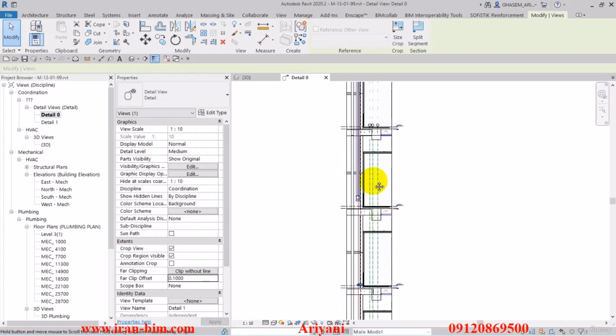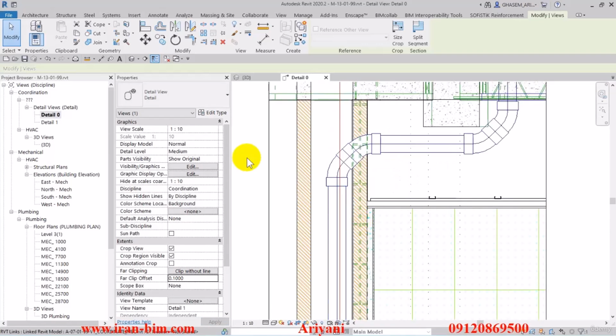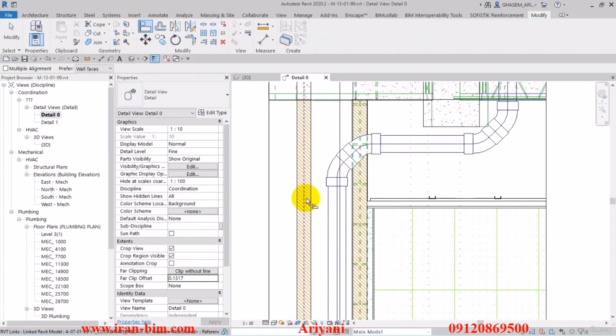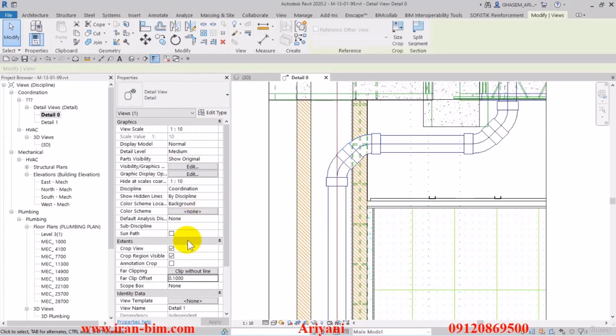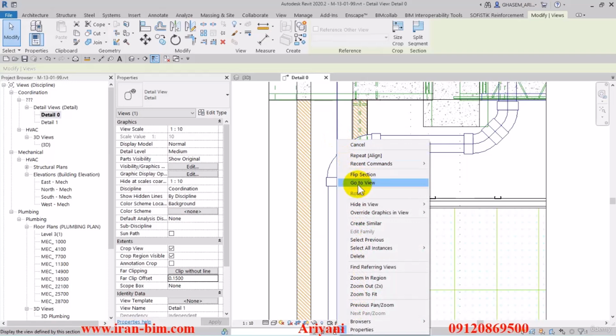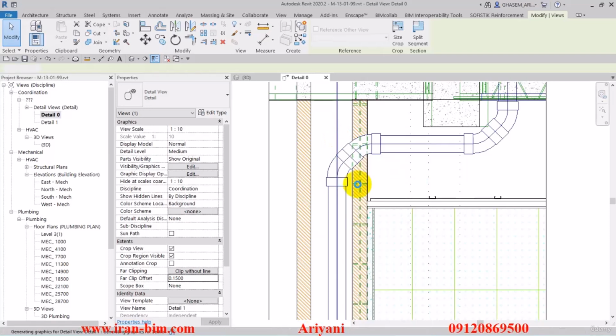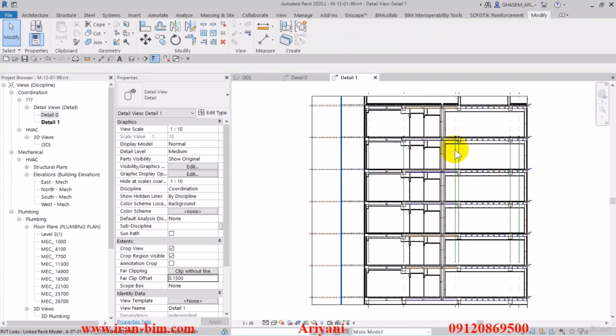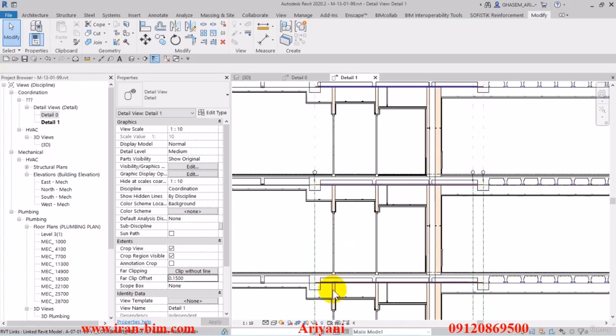And then I'll scroll up through the plan and then zoom in to see how I can use the align tool to lock the center of this pipe with the cut line that we just made. Then select this and put the offset on 15 centimeters. Alright, so right click on it and hit go to view. Alright, now on this plan that opened up, I'll put it on fine. And then let's see where we can find it.